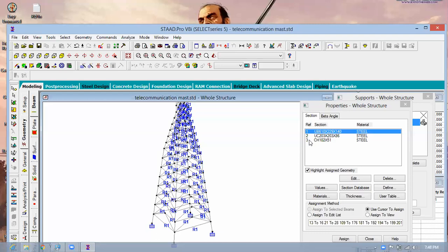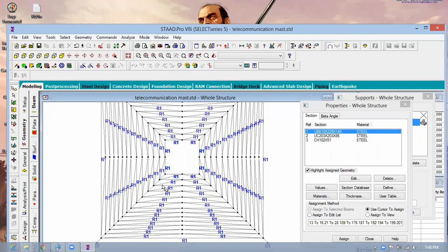So the next thing is our columns. For me to assign to our columns, it is not straight. So I'm going to go to the Y axis, Y view, global view, Y. I want to drag up my screen a bit.